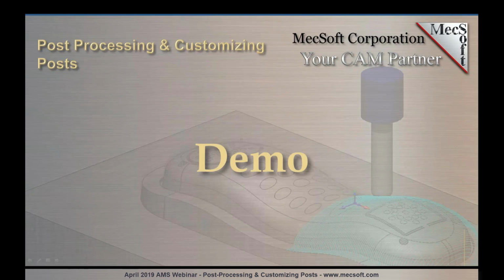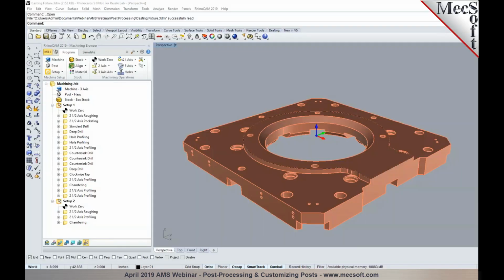So the first thing I'm going to do is give you a quick overview of the post-processing workflow. I currently have a part already programmed in here, and this is RhinoCAM 2019. As you can see, there are several operations that we have programmed in here, starting with roughing, pocketing, several different hole making operations like drilling, hole profiling, and then countersunk operations, deep drill, a few tap operations in here, and then profiling. As you typically would program your part, you would go through the process of creating all your machining operations in here.